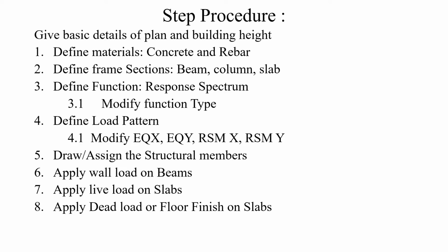And we have to define the load patterns. By default, ETABS defines the dead load and the live load. We have to define the wall load, floor finish and the earthquake load in X direction and in Y direction, and the response spectrum method in X and Y direction.